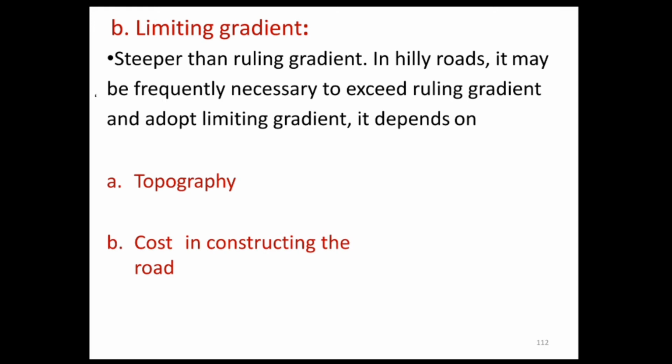With gentler gradients on hilly roads, it may frequently be necessary to exceed the ruling gradient and adopt the limiting gradient, but care should be taken to separate such stretches of steep gradients by providing either a level road or an easier grade.